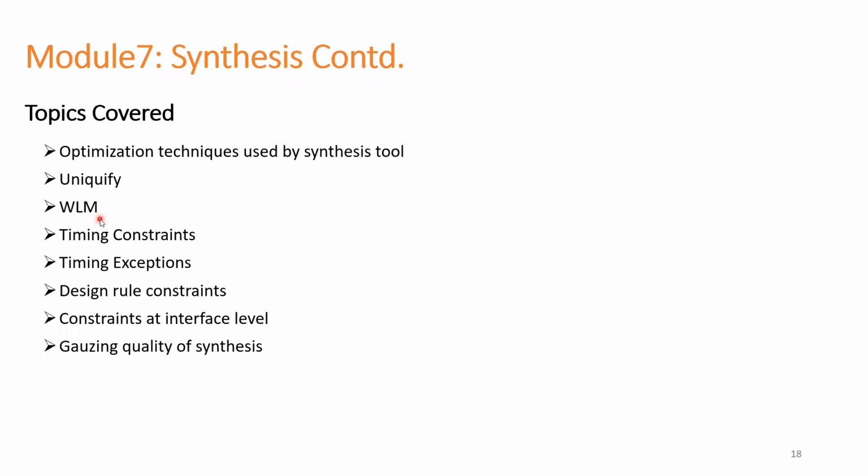So wire load module, it is again zero wire load module. So the interconnect delay will be zero at synthesis stage. Timing constraints. So in the timing constraint file, that is SDC, design constraint file, the clock definition will be written, clock uncertainties such as setup uncertainty, hold uncertainty, and case analysis information.